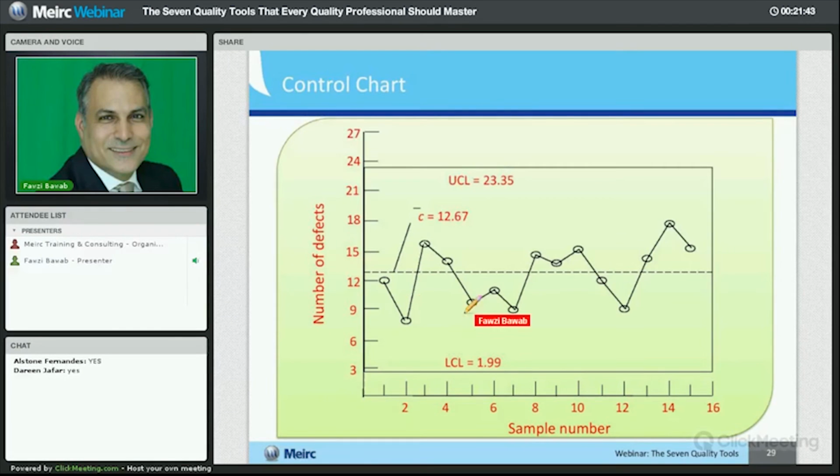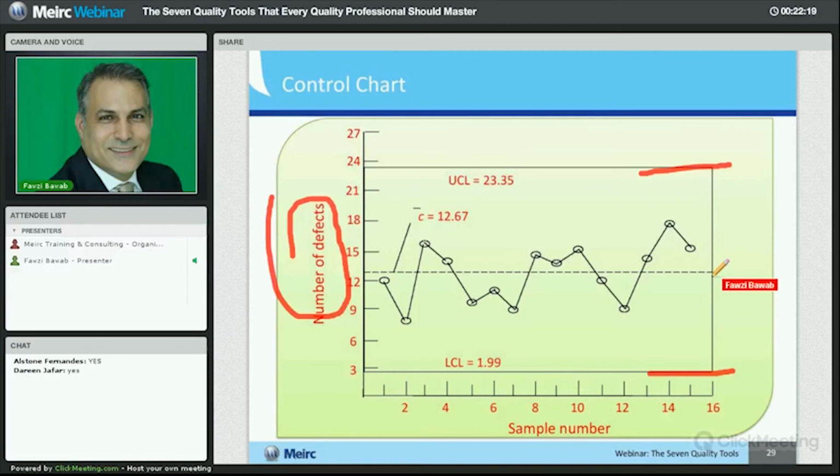And here's an example. This is one type of control chart. You can see the process variation. Now, this type of variation would be accepted as normal variation. You can use it here to understand that the process is showing variation, but still within my limits. And that is telling me that the Y or the metric I'm looking at is showing what we call normal variation. Now, my objective, if I'm looking at the normal number of defects here, will be to establish later on maybe a reduced chart, so we can reduce the number of defects over time.